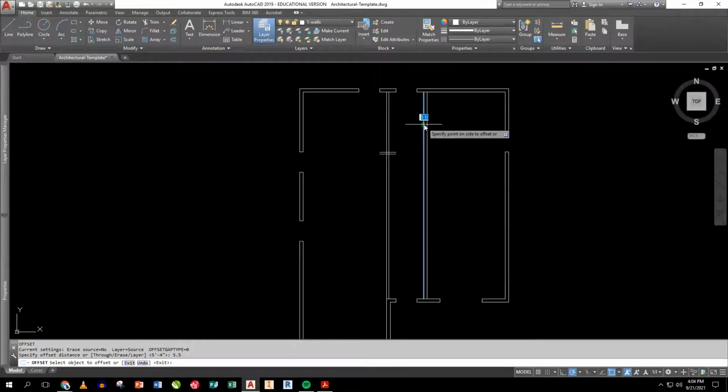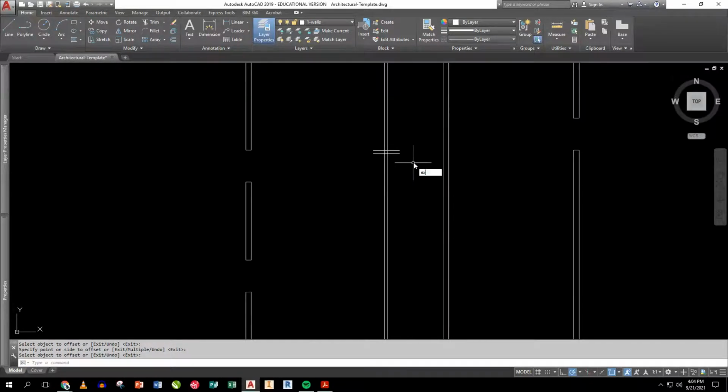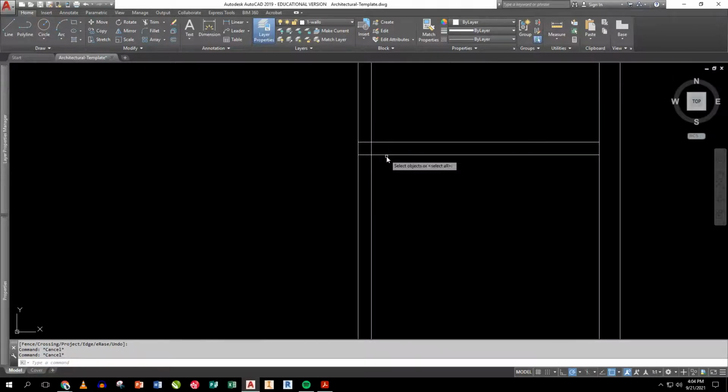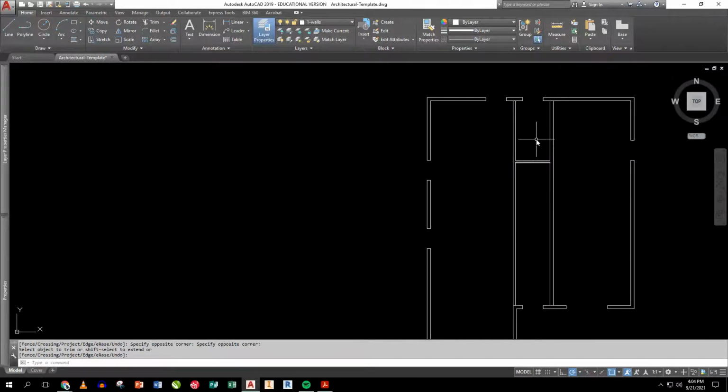This is a plumbing wall here because it's going to have the drains and stuff in it. So now I can extend, EX, enter, enter, because it's just like the reverse of a trim, and extend that out. I can go trim, enter, enter, and get rid of this out here. And if I really want to be obnoxious, I can start trimming out these little pieces in here. Okay. So there is my plumbing wall.